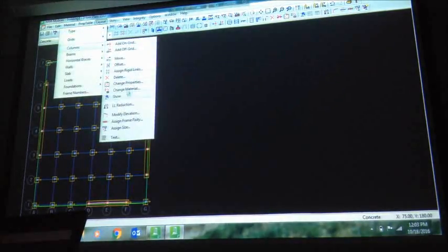Yes. For that orange looking box for the lateral load or something, the one on the walls, if you messed up, is there a way to delete it and then redo it? Because I drew mine too short. Messed up with what? I only went from 6 to 5. I didn't go from 6 all the way to 3. Doesn't matter. Leave it like that. But what you can do, 6 to 5 is fine. What you need to do is go to layout and make the columns, change properties, and click on those columns which are not lateral. And same for the beams also. Okay.